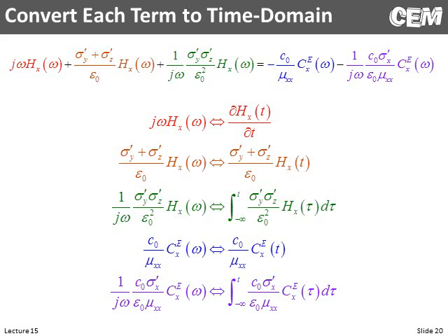One thing I'll point out is that notice these integrations are only non-zero inside the PMLs because we have these conductivity terms here, and there's another one. So outside of the PMLs, this integration is just always zero. So in fact, it's most numerically efficient to only perform these integrations in the PML regions rather than integrate everywhere.